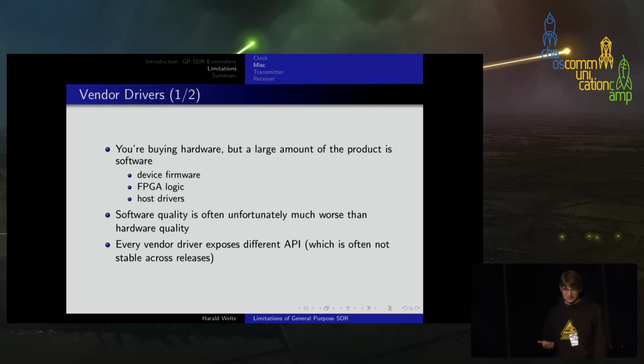Which brings us to the topic of vendor drivers. If you're buying a general purpose SDR, what you're getting is not just hardware, but of course lots of software that runs on your host PC, software that runs in the FPGA, in the gateware, in the controller, whether it's a microcontroller or a soft core on the device.